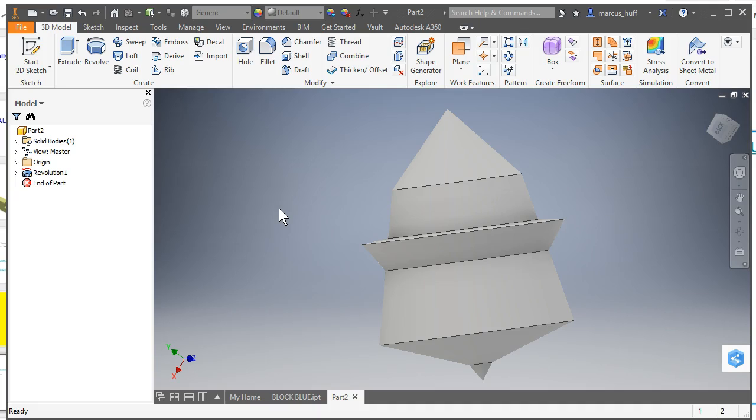The thing is, as you use Inventor, when you do these drawings and revolutions and things, it's adding these constraints automatically in the background, and sometimes it can get really difficult to work around those, and until you've had more practice, it's really not very useful to struggle with that. So a lot of times it's just easier to abandon it and start over again and do it right.